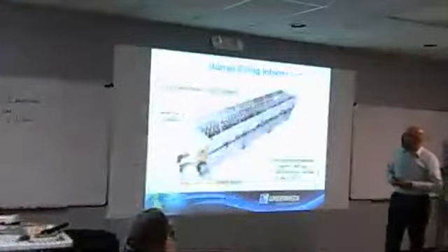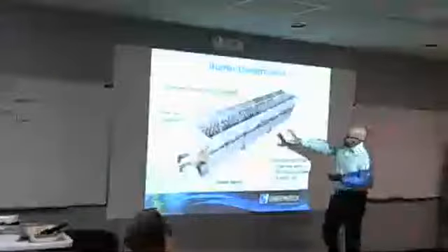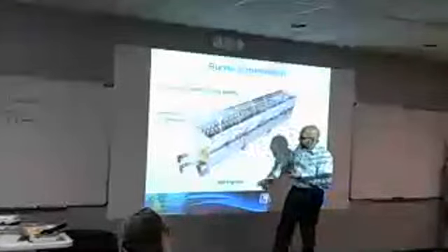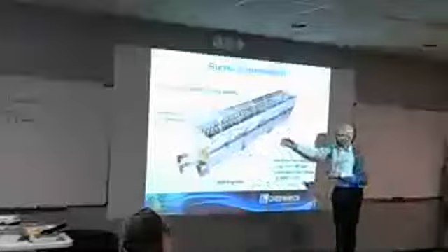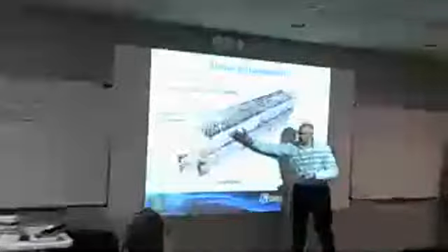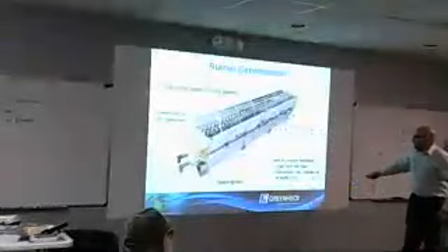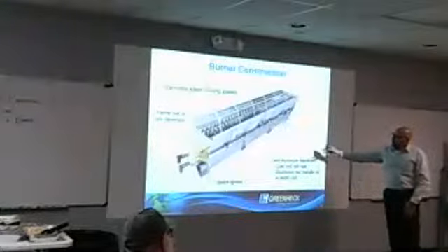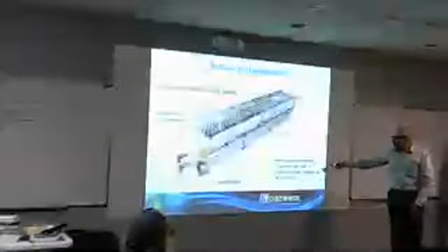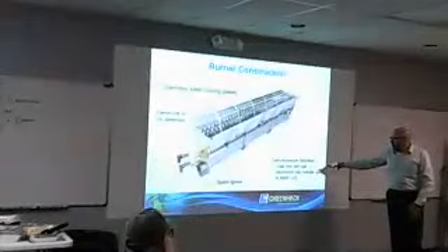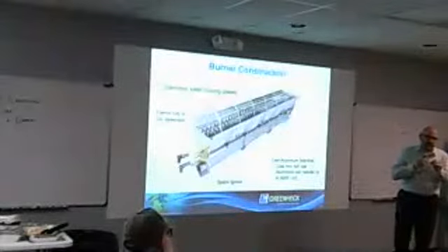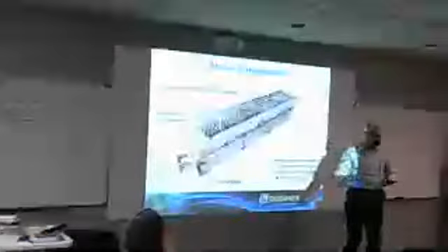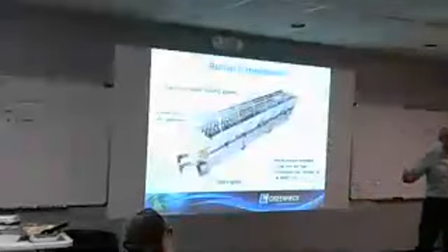So that's a close-up of the manifold itself. Stainless steel mix I mentioned a little bit earlier, the flame rod or UV detection to make sure that everything's firing correctly, the spark igniter, and then the manifold at the bottom where the gas is going to come in and begin combustion. Cast aluminum manifold is important versus a cast iron. Manufacturers choose one way or the other. The challenge with the cast iron is that over time, the little orifices will begin to rust and they'll plug. And so now you begin to lose firing capacity because of the rust in the holes. So then you have to go in and clean those out or replace the burner.